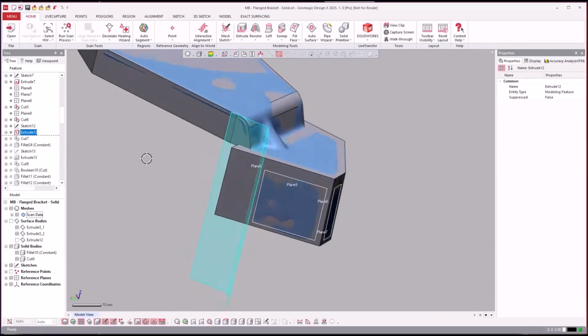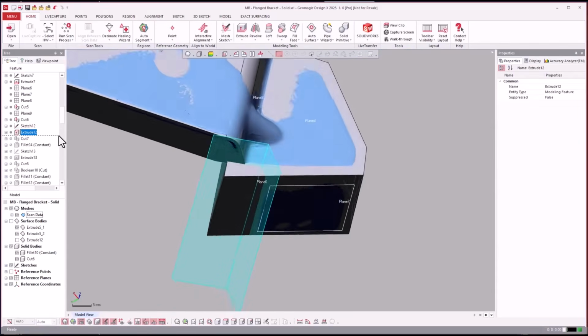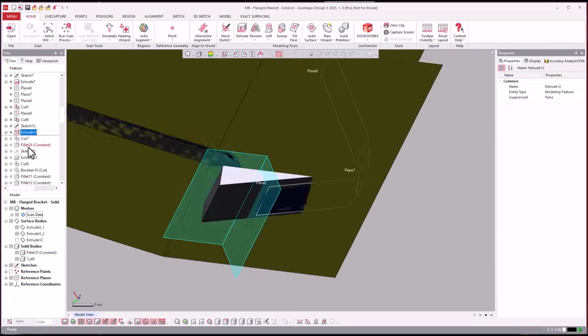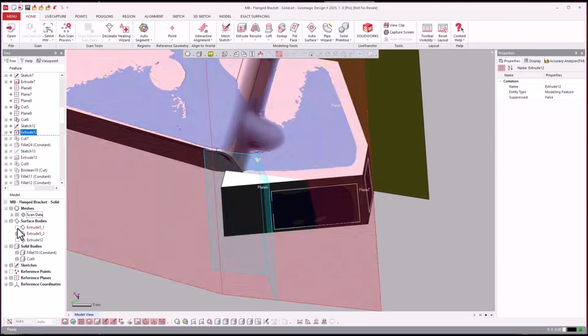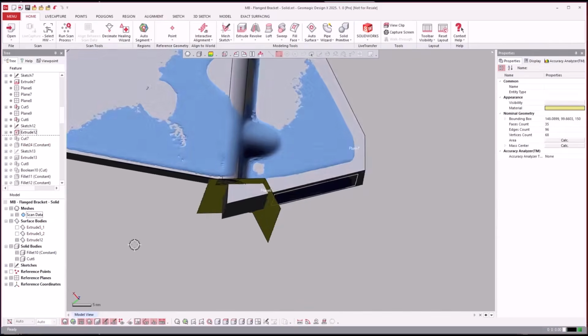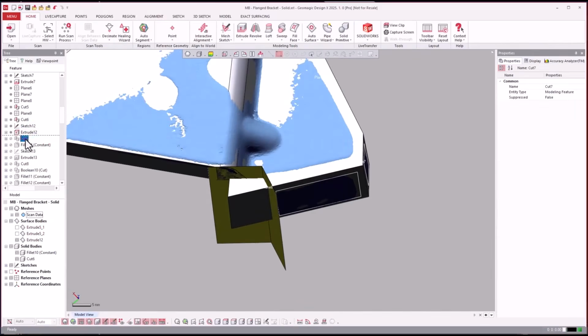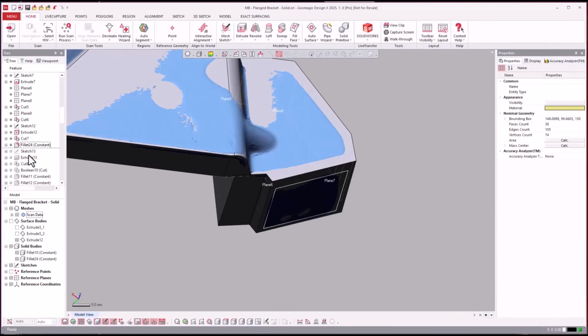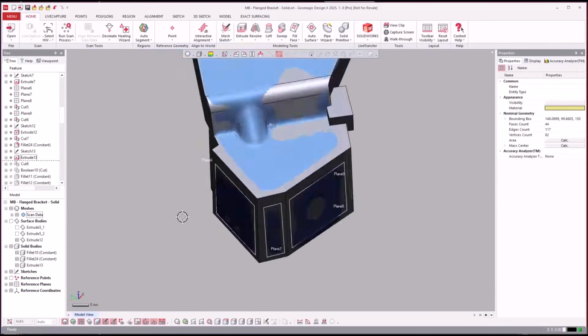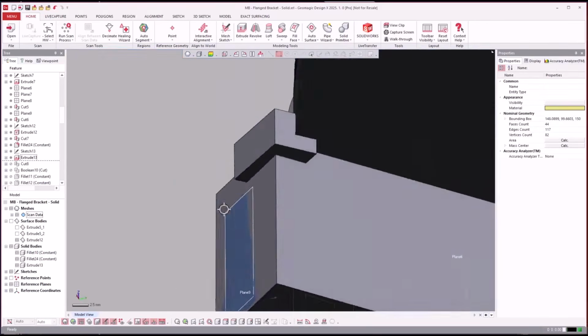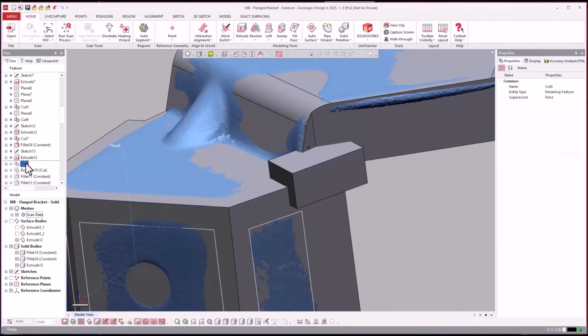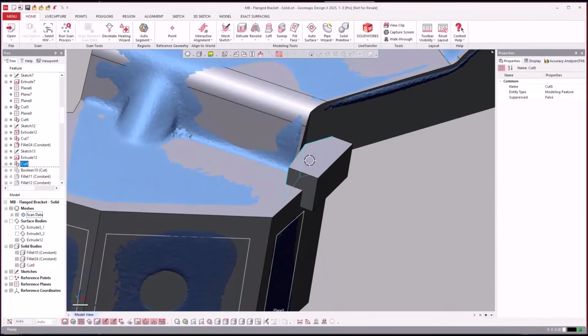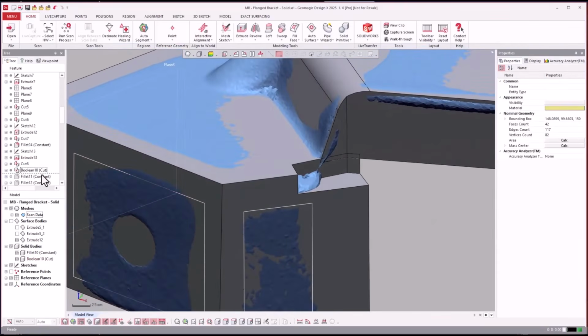Now we can go back and we just fit a surface extrude here, like so, and then cut it away. And now jump forward. We'll just do a fillet there and jump forward. Now here on this side, we went ahead and we're creating a tool body and cutting the tool body and then booleaning the tool body from the main piece there.